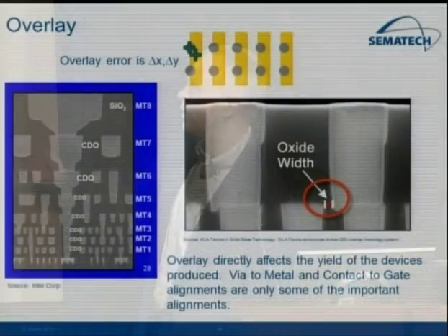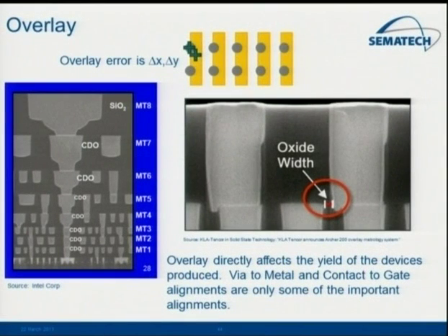So that was measuring a line size and measuring a line profile. As I mentioned before, another critical part of dimensional metrology is measuring how well two layers line up. And you have to do this because you have 50 or 60 layers sometimes in a modern process. Here's an example of a fairly old microprocessor, but it already has 8 levels of metal. And so you need the alignment between each of the metal levels, and the metal and the via levels, and the metal level and the transistor down here. Those all have to be controlled within nanometer scale precision.